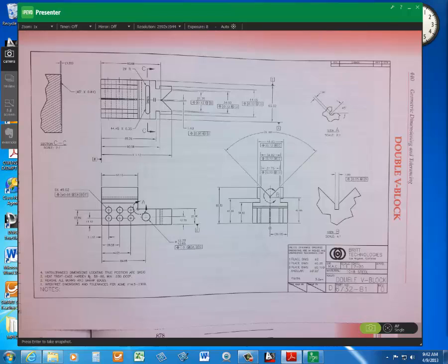All right. Then B is positional tolerance at the possible produced sizes for that dimension. So let's see. It's a hole. So at 12.65, it'll be 0 position tolerance. Then as we move away from there, increase, then we're allowed to add. Okay.